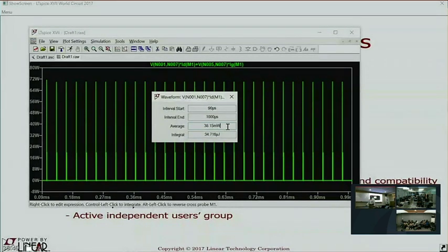I can walk up to the switch mode power supply and wrap a paper clip between the output terminals. It will actually operate at current limit into that short circuit, and the top pass transistor runs cooler than under normal operation. That's why I'm a fan of frequency foldback. And yes, it runs at the wrong frequency. But if your rail is low by a factor of 3, your system isn't running yet, so where your EMI products are sitting, you probably don't care. So that's why I'm a really big fan of frequency foldback.